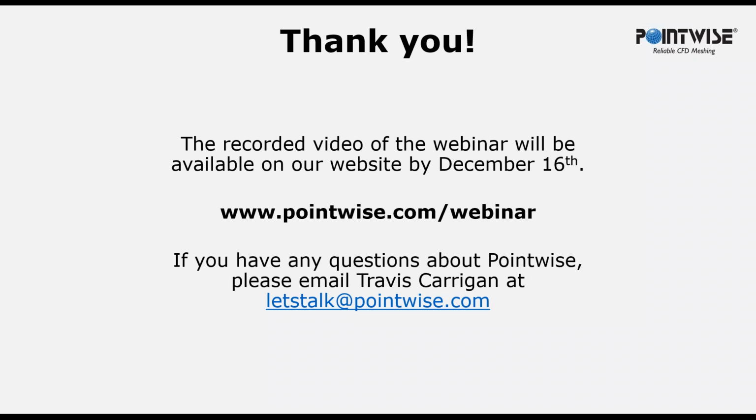Our next question is about Fun3D. I use Fun3D, which expects triangular unstructured. Can you diagonalize the square mixed cells to make it all triangles like you can for a structured grid? Yes, you can. Travis showed you one way to diagonalize the cells, which was to use the Grid Solve Attributes panel with your quad dominant domains and simply select triangles, then initialize, and that would give you a triangular mesh but with the same vertex locations you had with your advancing front ortho mesh.